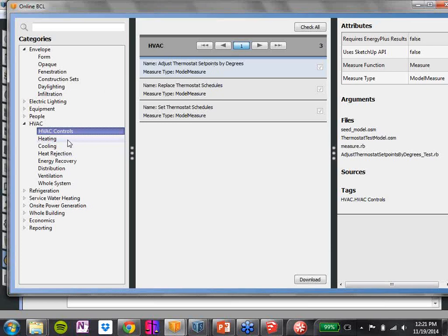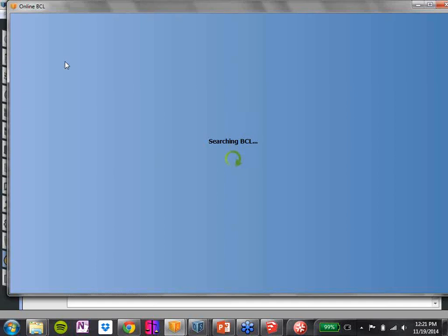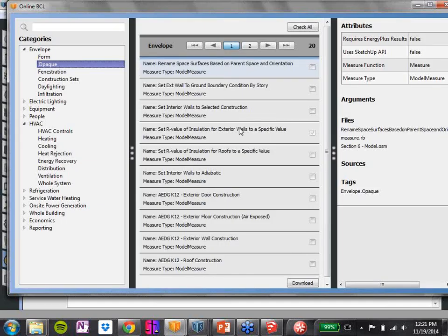is there's the default schedule that EnergyPlus runs, which is wildly different than how the building is actually run. And until you start breaking that down by hourly and start calibrating that model, that's not something that's going to be immediately apparent. So start playing with your schedules, but as opposed to doing that one at a time, we can do dozens at a time. For a simple example, I just downloaded changing the R value of the exterior walls.